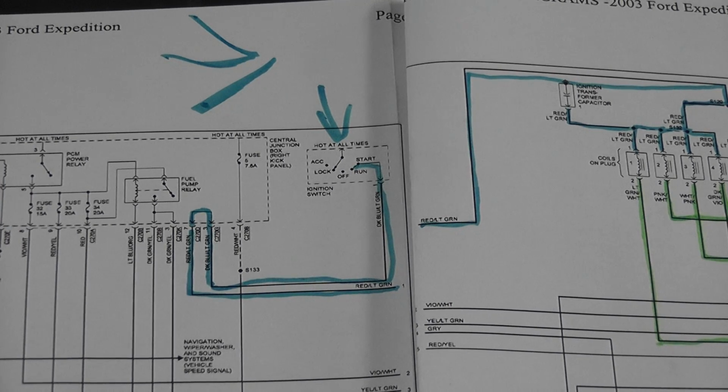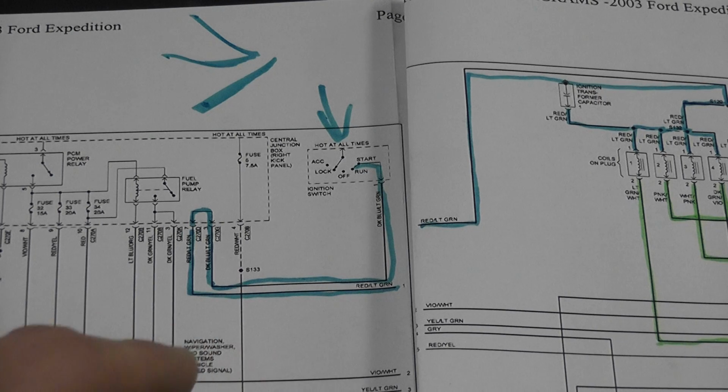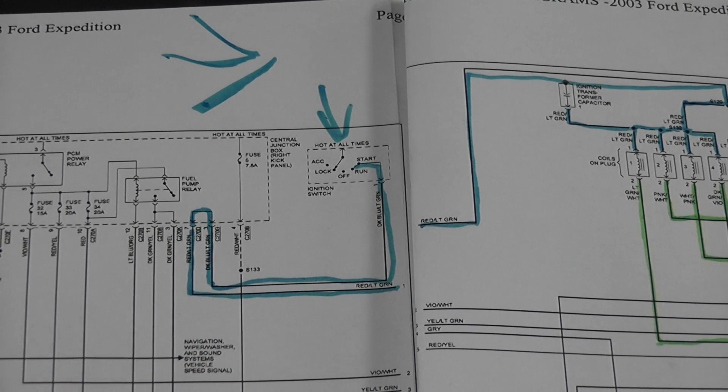And so what we did is we actually were able to easily dig that wire out of the main harness that runs down the column for the ignition switch, and that's where we adapted our amp probe for our current ramp measurement. So we'll be able to read all of the coil firings, the current flow on the primary, coming from that wire on the ignition switch. I'll give you a shot of that wire real quick.